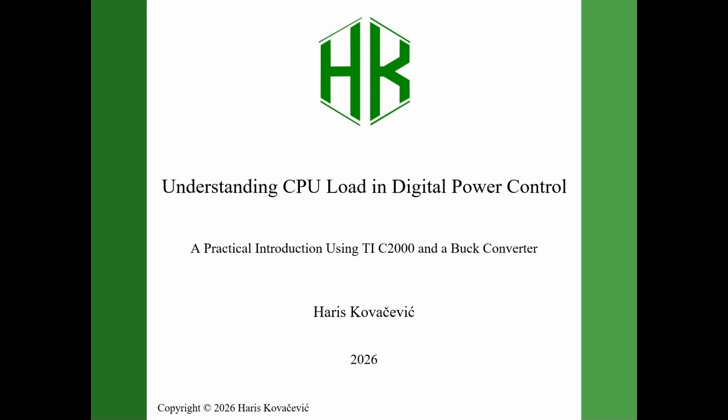Imagine your converter is switching at 200 kHz. That gives your microcontroller only 5 microseconds to sample the signals, execute the control algorithm, update the PWM outputs, and get ready for the next switching cycle. But how do you know whether those 5 microseconds are enough? How can you tell if your software is close to reaching its computational limits?